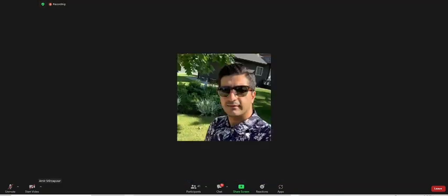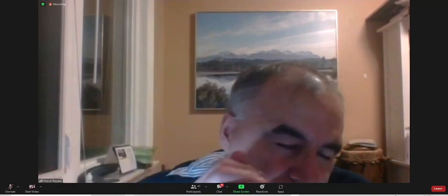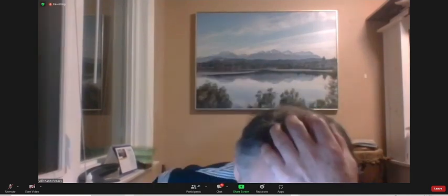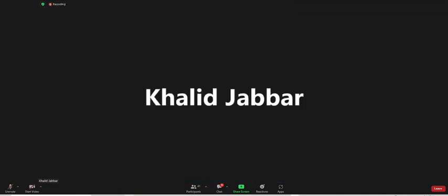How are you going to pass? We should put the elbow at 45, so you have to put two elbows. Each elbow is 10%, so it's going to be 20%. So when you have an offset, you should deduct 20%, and the length of this horizontal is the same. Now C.2.7.